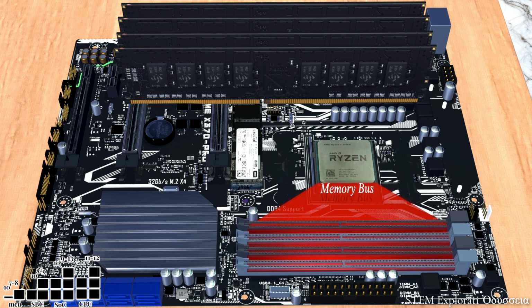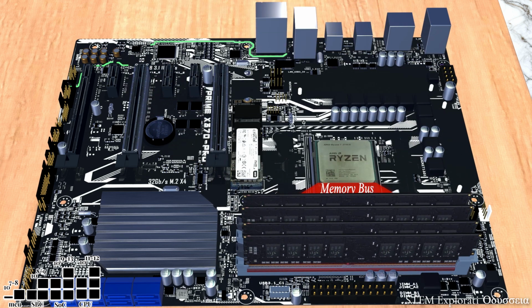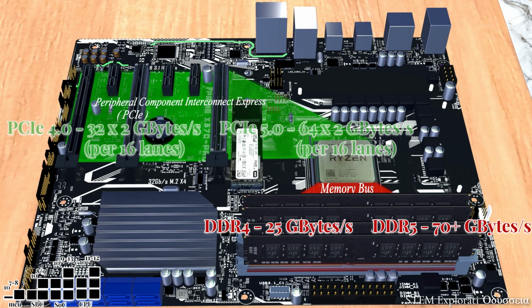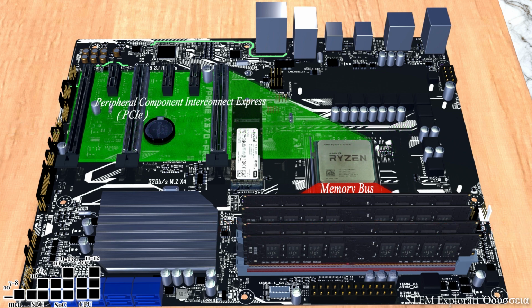And next, the memory bus is the superhighway between the CPU and RAM. For example, a DDR4 bus can move over 25 gigabytes per second. DDR5 pushes things even higher, well beyond 70 gigabytes per second. But modern PCIe lanes are now even faster in raw bandwidth. A PCIe 4.0 bus moves about 64 gigabytes per second, and PCIe 5.0 doubles it to over 128 gigabytes per second. This is why today's GPUs and solid-state drives rely on PCIe. It gives them the data fire hose they need to keep up.